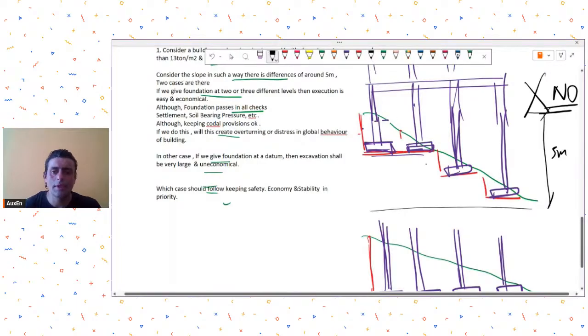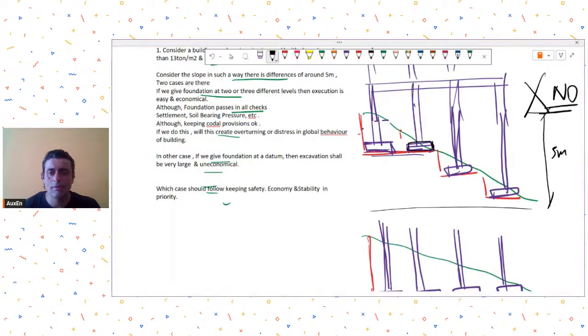The problems are that this footing will be very close to this edge. So because of the bearing pressures, there is always a tendency of this soil collapsing. So then here also, I assume you have not considered the requirement for retaining walls on these edges. And when you start considering the requirement for retaining walls, then automatically your costing will also go up.